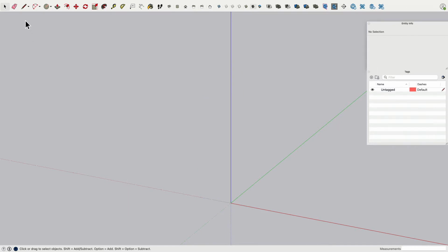Let's do this actually in 3D just as an exercise. So from here, from the center point, I go along the blue line, or I press the up arrow key, 21, enter. Then you see how sometimes this is now red. This goes along the red axis. So the right arrow key does that for me, locks it to it, 8 inches. Then up key down, 7 inches, escape from here, click to the left, 6 inches along the x-axis, and I can connect it. Cool. So this is actually a nice profile.